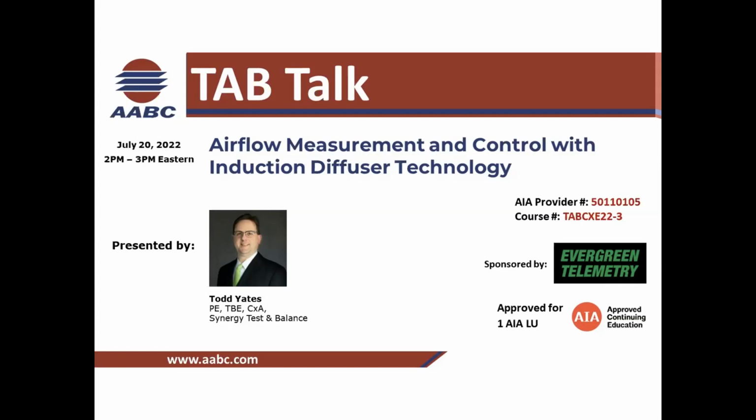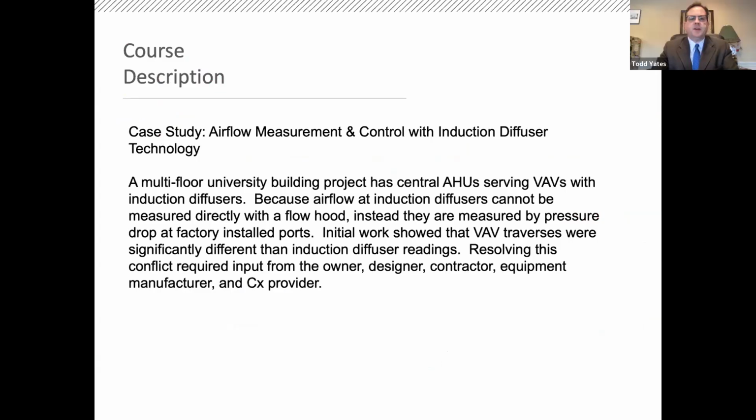Thank you. So the description of the course today is airflow measurement and control with induction diffuser technology. A little bit about this building. It's a multi-floor university project with central air handlers serving VAVs tied to induction diffusers. Because the airflow in induction diffusers cannot be measured directly with a flow hood, they have to be measured with another method, primarily the drop at the factory installed ports.